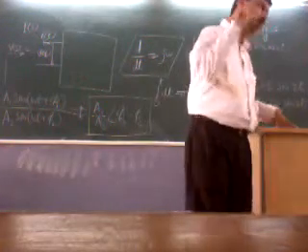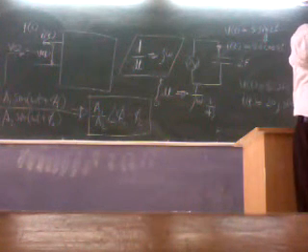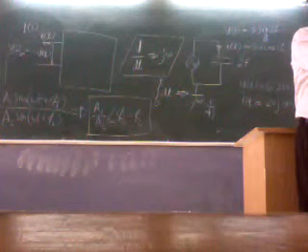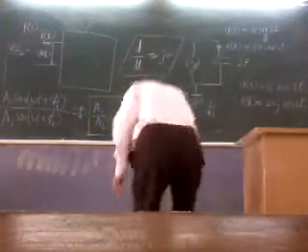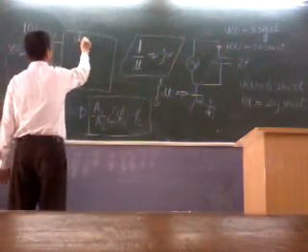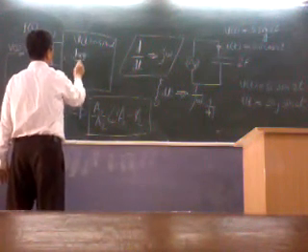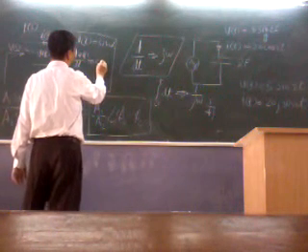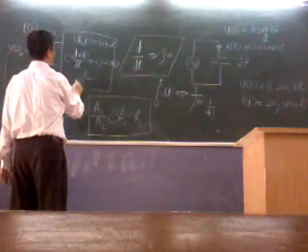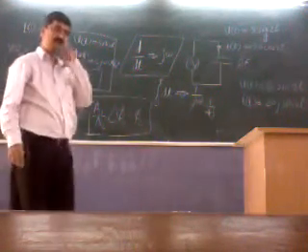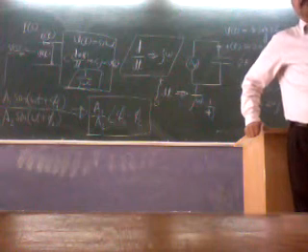Why? Because we have some Vt as say sin omega t. Then current is c dVt by dt, but dVt by dt is j omega Vt only, and c is there. That is equal to c into j omega Vt. So the ratio we take is 1 upon j omega c. That is impedance. In that way, we can define impedance for sinusoid.